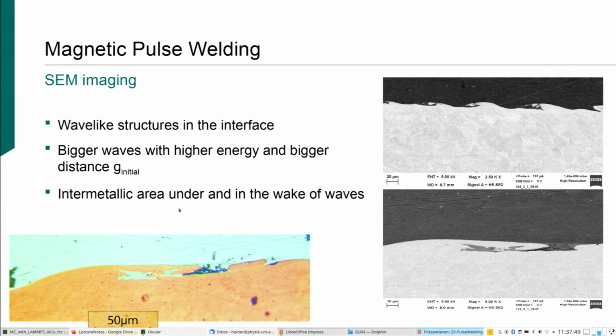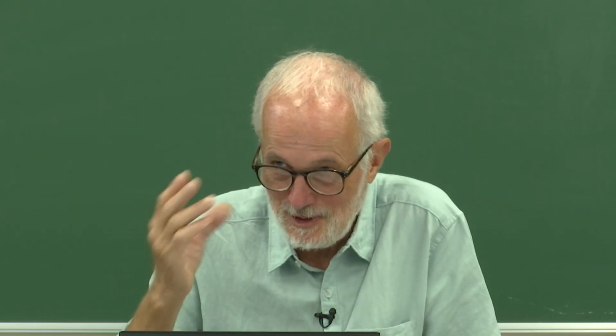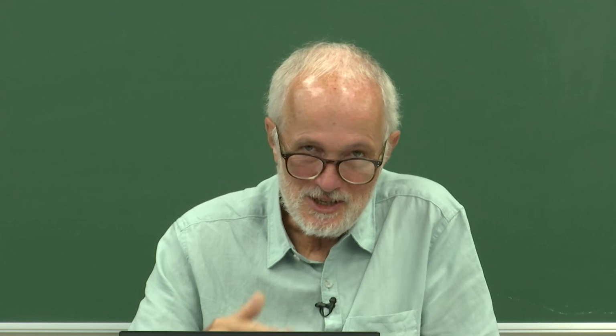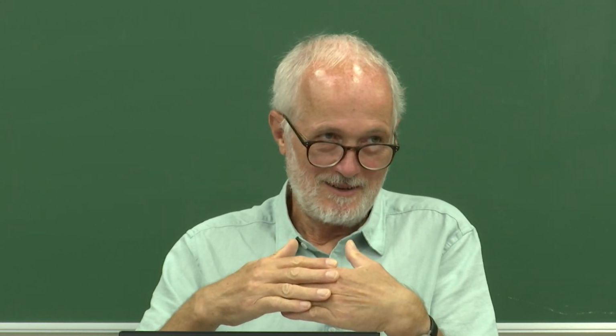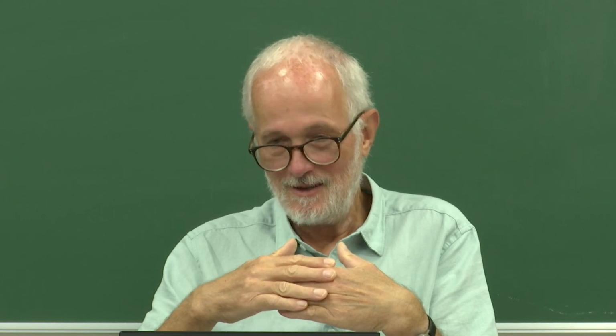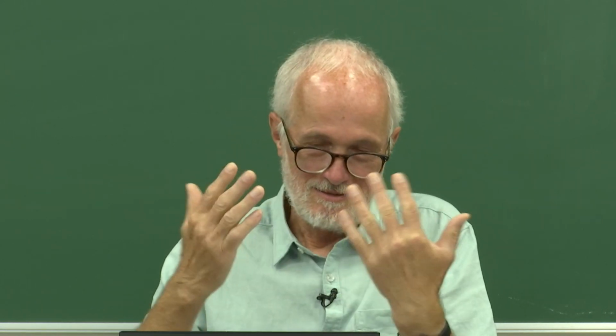And then the question we were interested in, I think that's visible here in this close-up: do we find at first intermetallic phases which form here in this joint? This comes a bit from our experience with friction stir welding. There we always found intermetallic phases. And the second question is, does the collision energy lead to instantaneous melting of one of the constituents? As we will see, it's not out of the question.